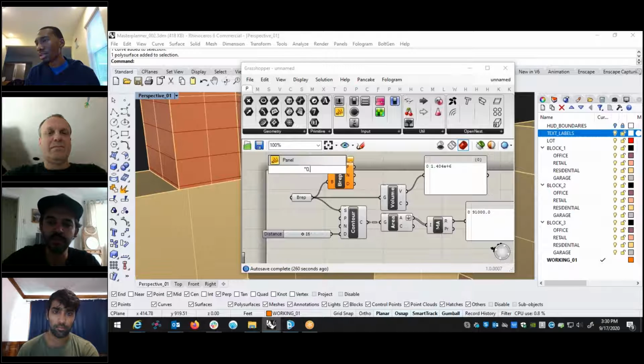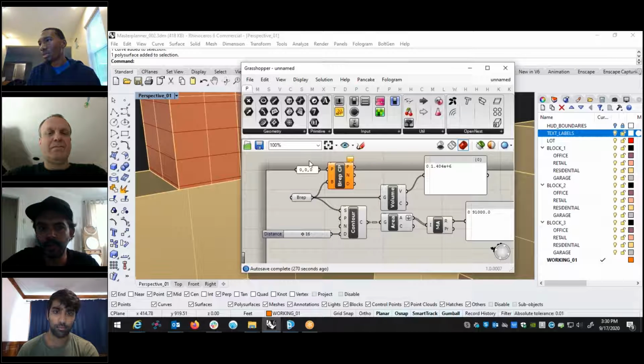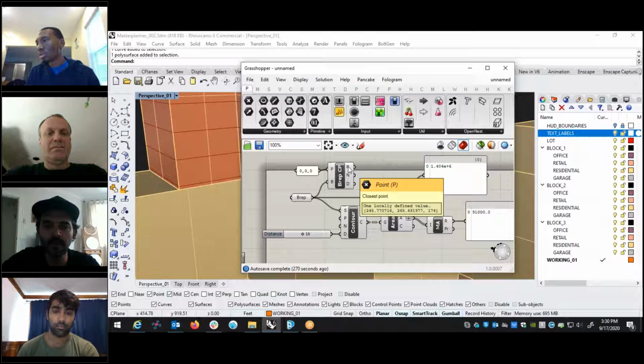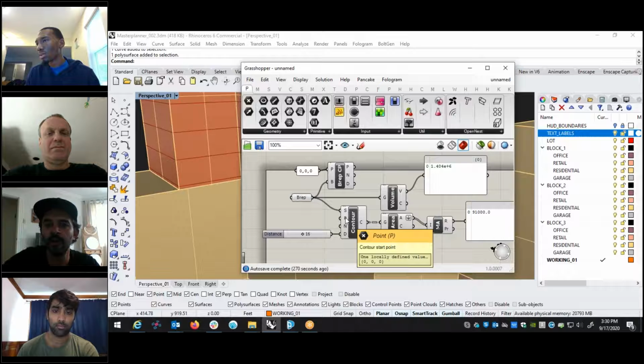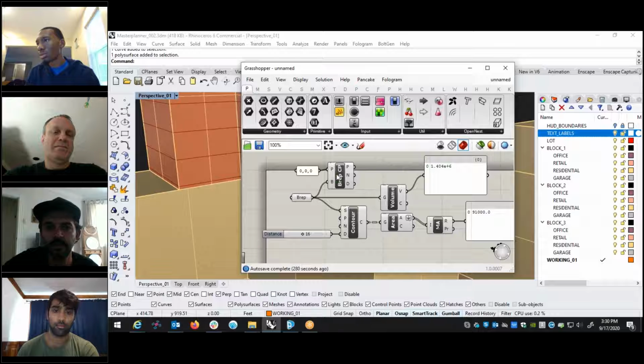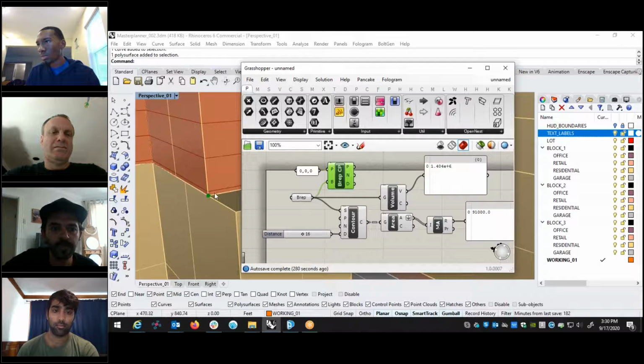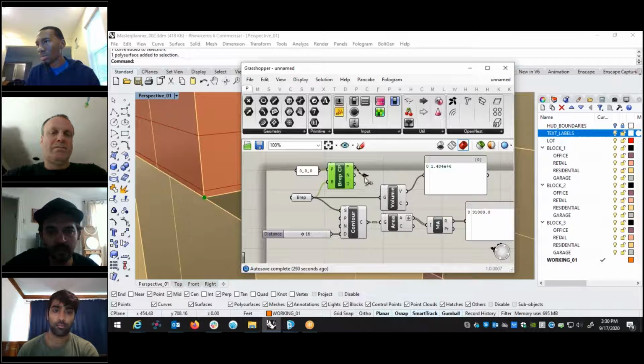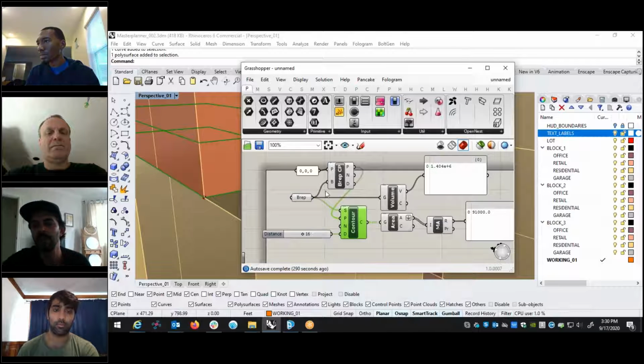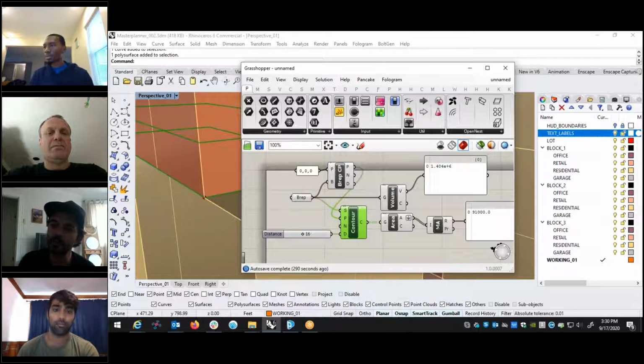I'm just going to use quotation 000, which is origin, and that's going to give me a panel that says 000. And so that point is the closest point, and on contour, it says, where do I start? Right now it's saying start at the origin. And I'm saying don't start at the origin. Please start at this point. So if you look real close as I connect point to point, now that contour is right there, right at that point, which is exactly where I want it.